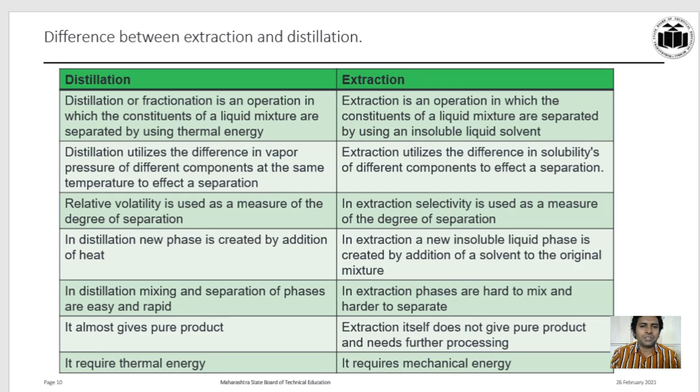Distillation, or fractionation, is an operation in which the constituents of a liquid mixture are separated by using thermal energy, and in the case of extraction, the constituents of a liquid mixture are separated by using an insoluble liquid solvent. Distillation utilizes the difference in vapor pressure of different components at the same temperature to effect the separation, and extraction utilizes the difference in solubilities of different components to effect the separation.